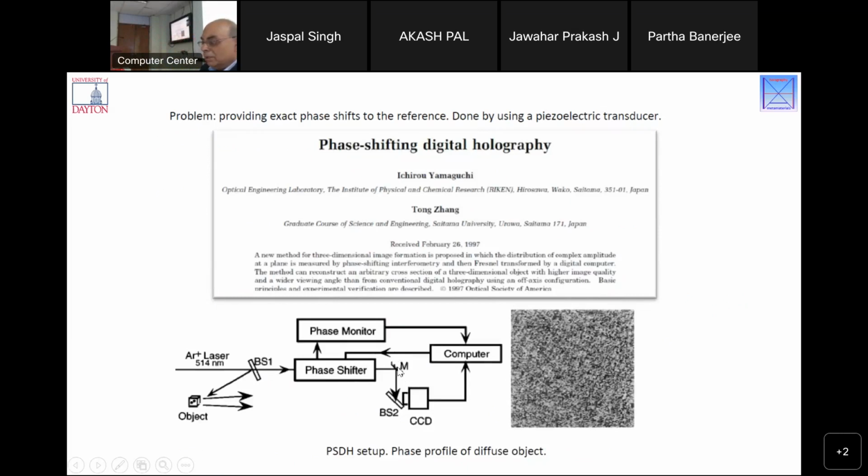In the schematic diagram, it is drawn as a phase shifter and then a mirror. That's not what is done in practice. In practice, there's no extra phase shifter, but you have this mirror, and that mirror is mounted on a piezo device. So the piezo device is moved. Now the piezo device can be moved by electrical voltage, and it can be moved by very precise amounts. And how much are you trying to move that? You're trying to move that by something like 0.5 microns.